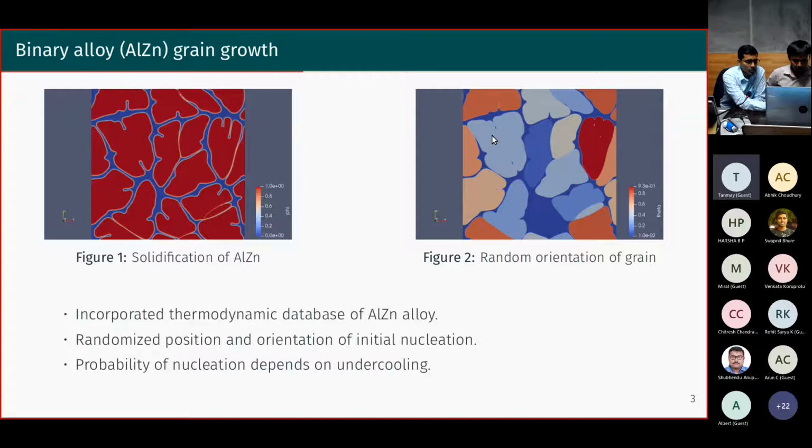In the orientation field based model we have an extra theta term, and we have only one phi field, which is 1 in the solid, 0 in the liquid, and at the interface region it would have a value somewhere in between. So instead of solving for n number of phase field parameters, in this type of formulation we just have to solve the phi evolution equation, the theta evolution equation, and then to accommodate the thermodynamics, we have to include the mu equation.